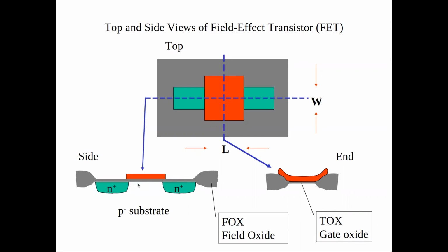Yeah, and this is an example of what it looks like when you deposit polysilicon on top of your very thin gate oxide, in reality, in practice. This is the way we draw it, but when you actually fabricate it, you see that there are all these imperfections that just come out of the fact that it's a physical device that is being fabricated through some lithographic process, bombarding things with ions and then etching things away and then masking them and so on.